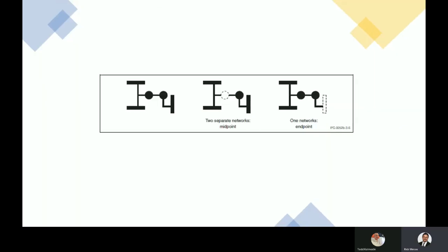Now, what is a net list? I don't know if many people watched our first podcast, but we explained what a net list is and what electrical test is. A net list is a connection between a couple of surface mount pads or some holes or via holes in a printed wiring board or PCB. A net list could have one node. A net list could be a single point net. So you have one pad, a surface mount pad, usually in a surface mount package or a quad pack or a BGA, where you have just a pad there to solder to. That would be a single point net.